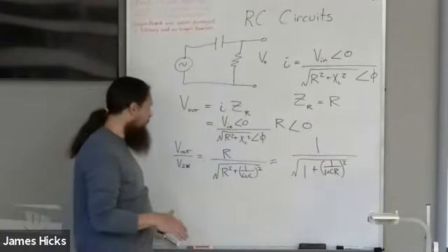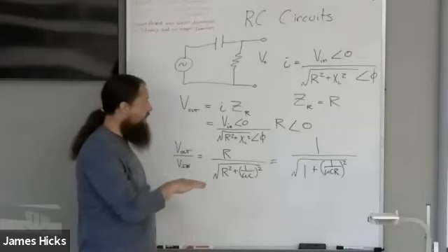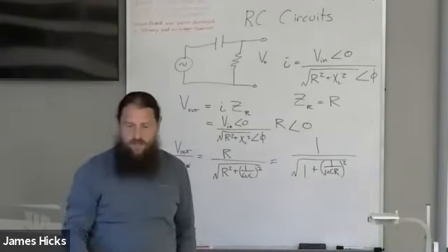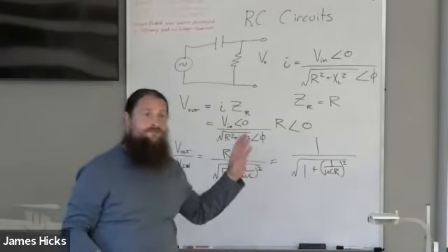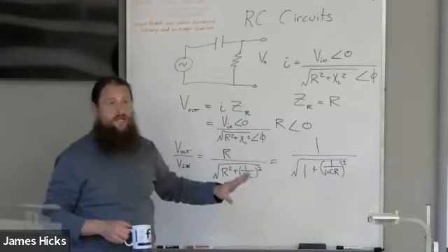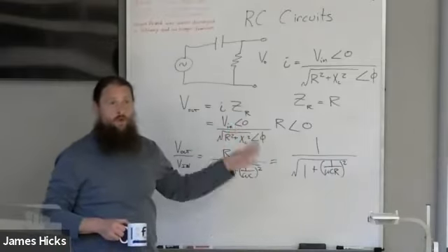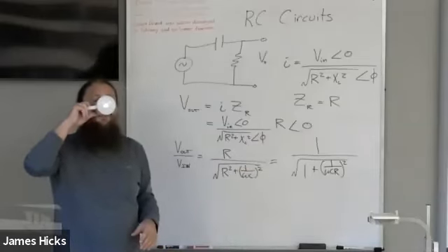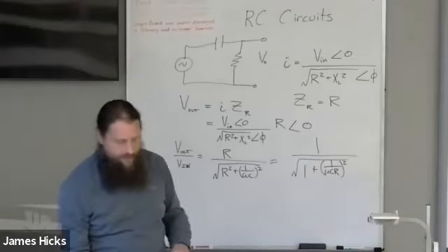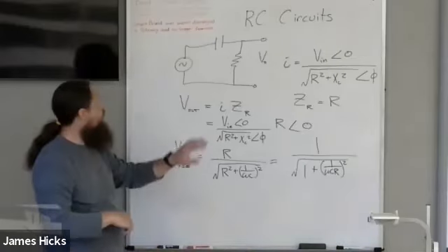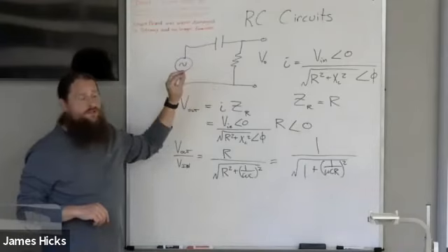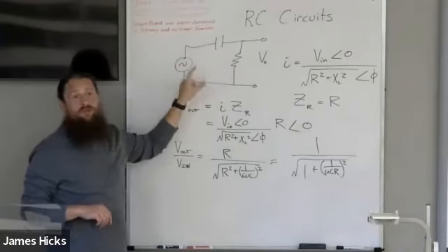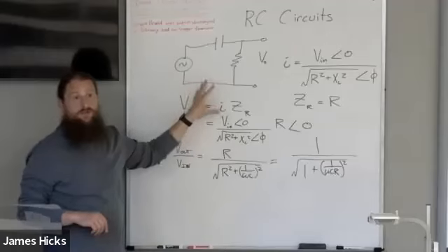So low frequencies get blocked out. Just switching over the other component, capacitor to the resistor, we went from a low pass filter to a high pass filter. Essentially, what we did here was a frequency dependent voltage divider.